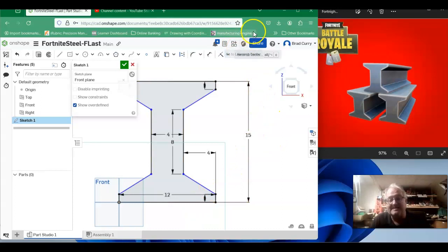I think at this point it's still easier to dimensionally constrain by using endpoints. So I'm going to go from this endpoint to here, and we're going to say that's 3.5. If you think about it, if we want 15 inches overall, we've got 1 inch here and 1 inch here and 8 inches there. That really means from here to here is 2.5, so 3.5 to there. If I take a look and say from this dimension to this dimension is 3.5, lo and behold it is, and we're equal on that.